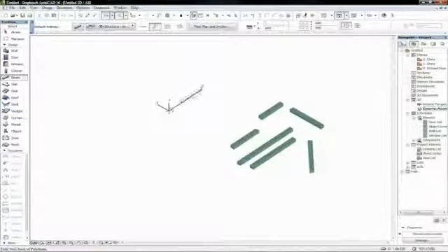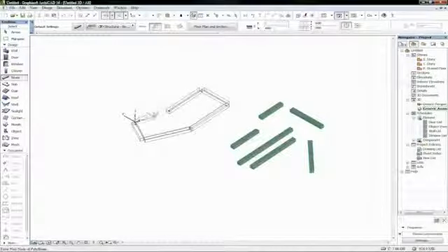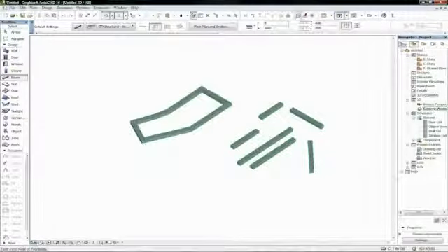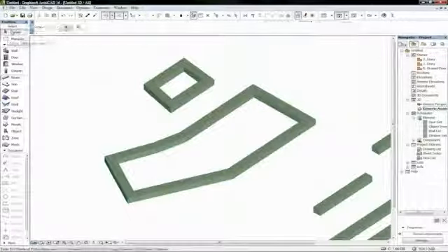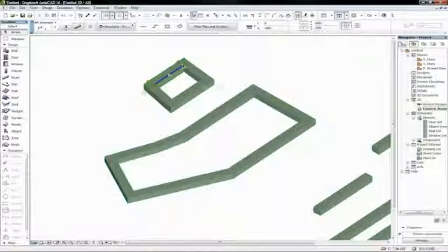With the other 3 geometry methods, chained, rectangular, rotated rectangular, you can create a group of beams. By using the chained method, you can make straight beam segments along a 2D polygon on a horizontal plane. As you can see, you can even use these geometry methods in the 3D perspective view. Note that new beams cannot be created in the section and elevation views.